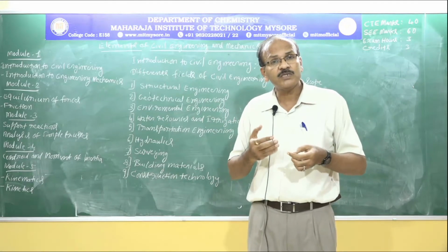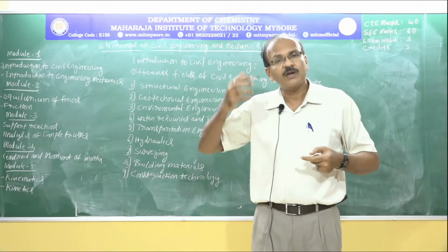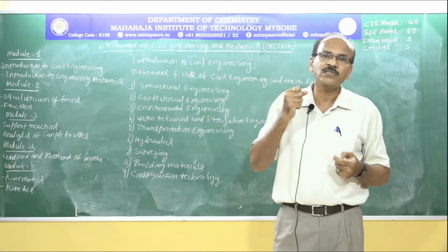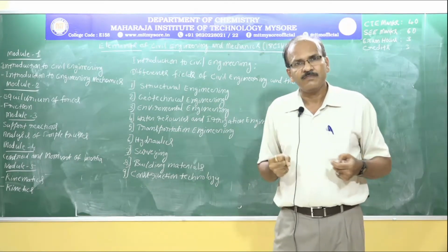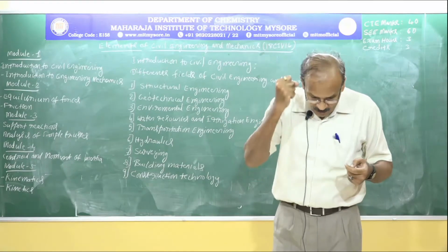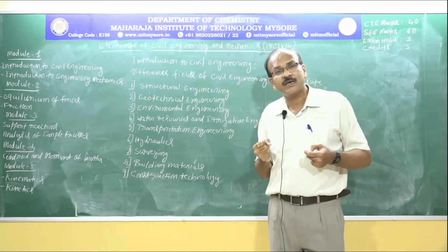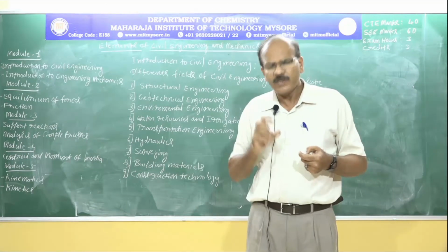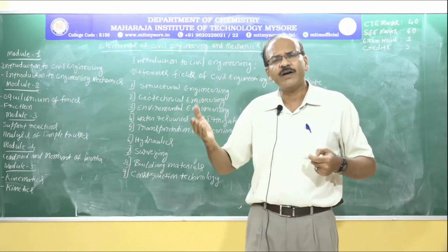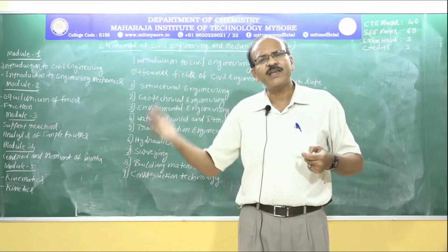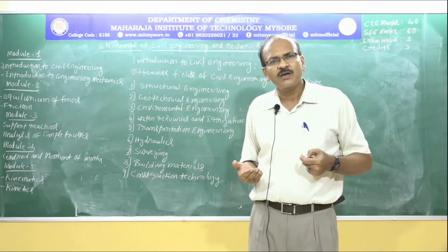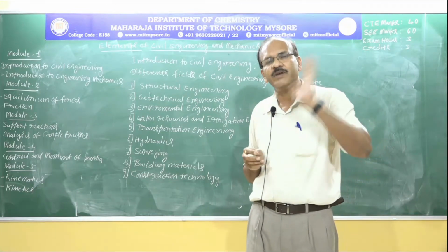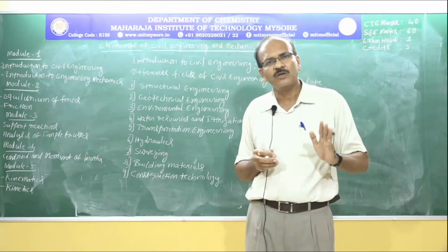So whenever we construct a structure, the first thing we do is soil testing. How do we do a soil test? We collect the sample and study different properties of that soil. Finally, we find out the safe bearing capacity of the soil, so that we can stretch the soil within certain limits under external load.